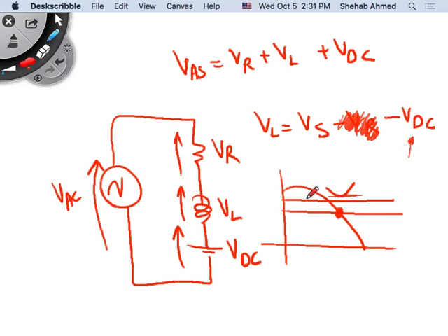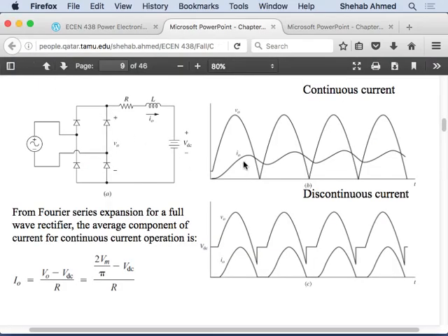Right? If I bring the DC source up, what's going to happen? I push it to the left. If it pushes this to the left, it means what? Current will have a slope of 0 before. So the idea of trying to tune it to fall, in this gap between the resistive case, can happen if you keep increasing the value of the DC source. Right? So increasing the value of the DC source will do what? Will push this current to the left, and the point at which the current slope becomes 0 will be moved to the left. At some point, you can bring the current down to 0.